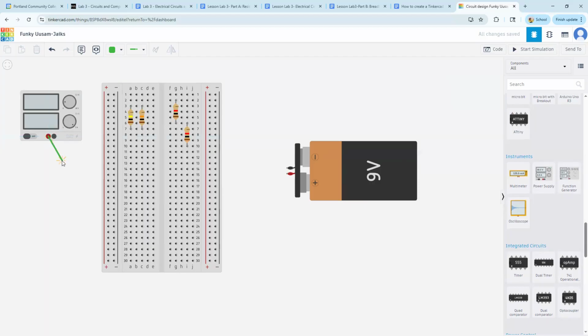You can just create wires, positive to positive. It can be any of these. So you can see the positive vertical lines are connected together. It shows you what poles are connected together. And then, so I can just click on here, then the negative to here. So right now we know that this is the positive and negative is like 5 volts, the difference between these two poles. And then I can start from positive, make a connection from here, like to here. So it's actually positive 5 volts here right now.